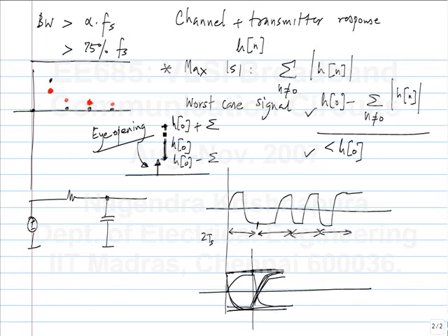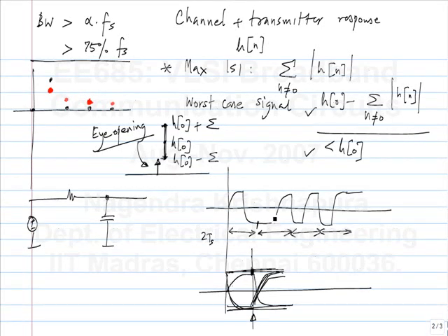Basically, this is just a collection of all possible y-axis values when we sample it. Now, this eye diagram is for continuous time. Let's say the sampling instant is here, then I can look at the thickness of this and determine how much the ISI is. So, I overlap the successive 2-bit intervals onto a single diagram.